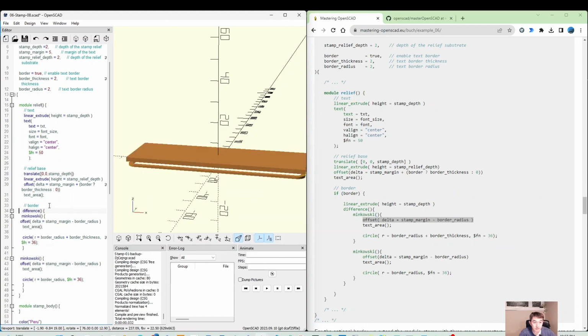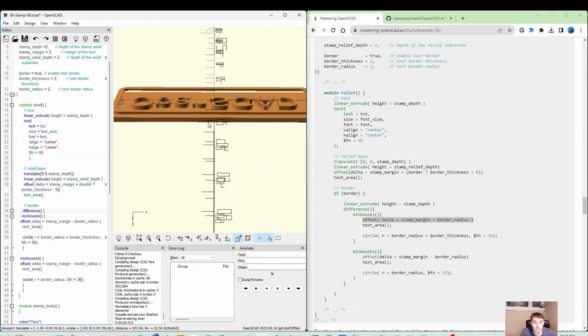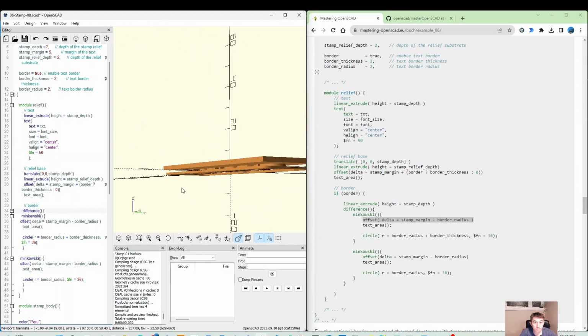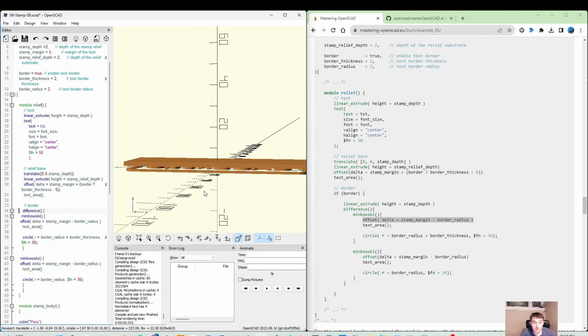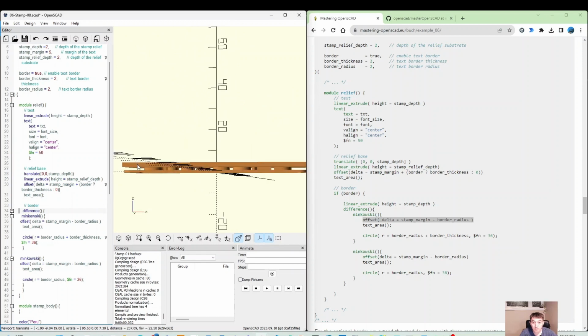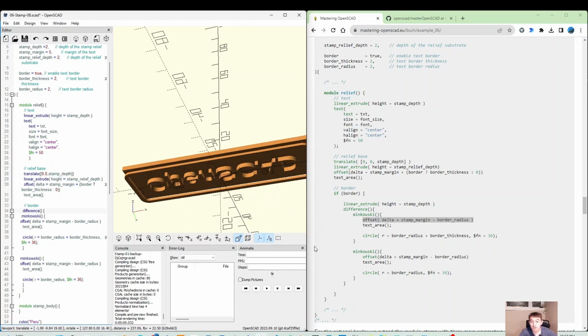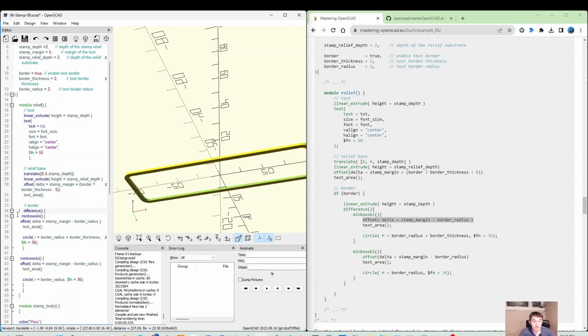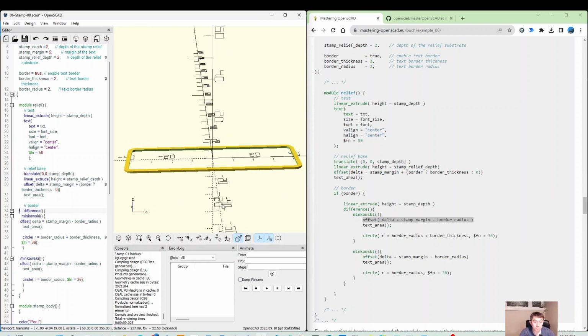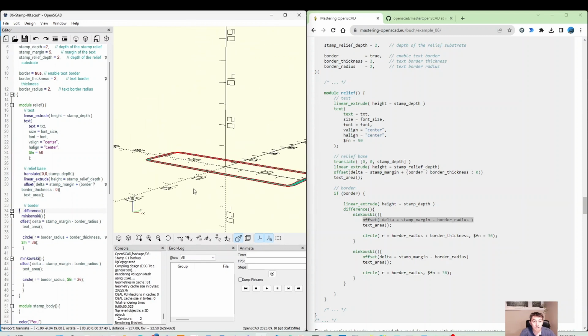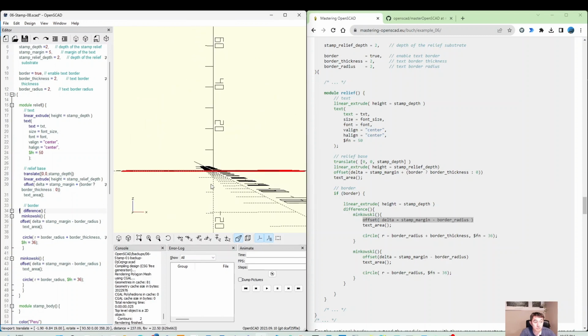And if we don't have that, this one is coming together with your existing one, and you can see here it is not connected. We need to make the linear extrude, because circle is 2D. If we don't do this linear extrude and we put this here and press F, you just get our 2D shape.